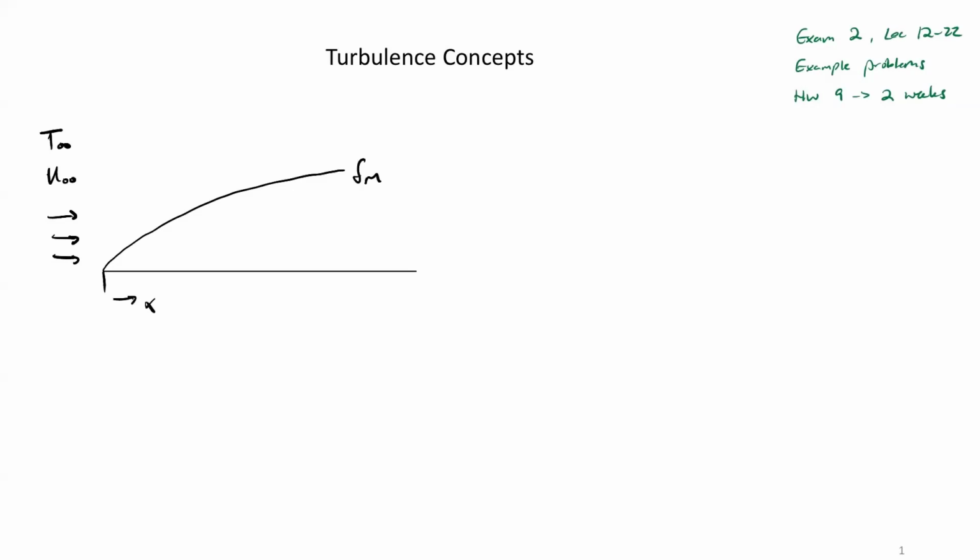What would we see? Well, right at the leading edge, we have a very thin boundary layer, and so there has to be a really steep gradient in velocity right at the leading edge. So shear stress is effectively infinite at the leading edge, and then you get it trailing off as you move in the positive X direction like this. All right, so this is our tau S as a function of position.